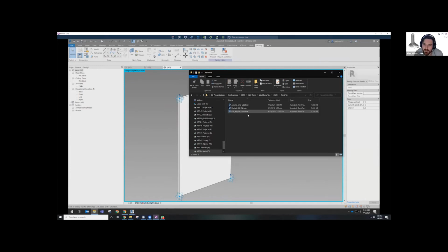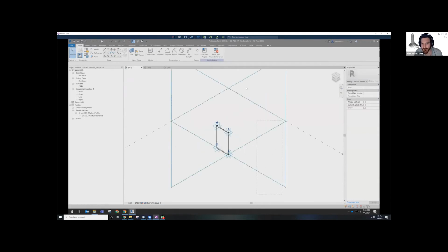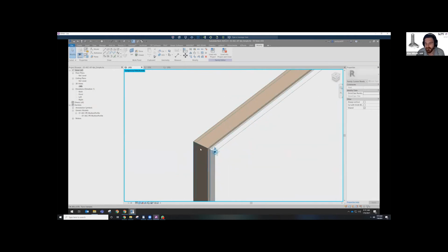Okay, Revit file. Oh, that's the overall families. The 4-point adaptive simple, this one, which I think I might even already have open. Here's one I prepared earlier. Okay, great. So this is the basic panel that I was talking about. You can see here that we have a basic form for the overall, which is the glass. If I just jump to shaded now, you can see here there's an extrusion for the glass, and then there's a sweep for the mullion itself.